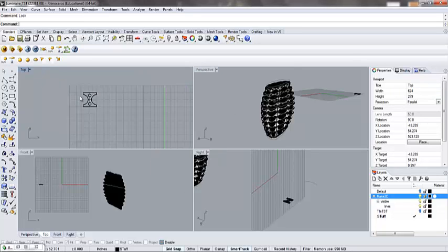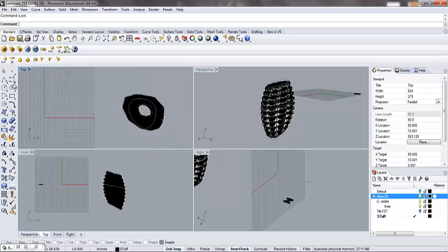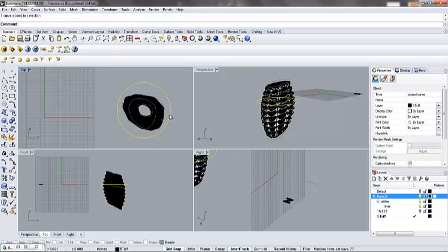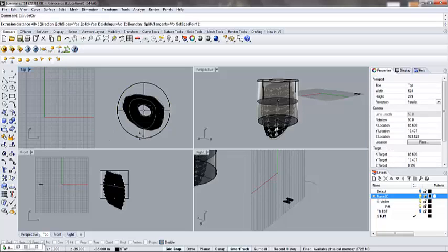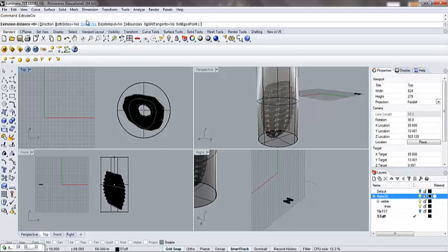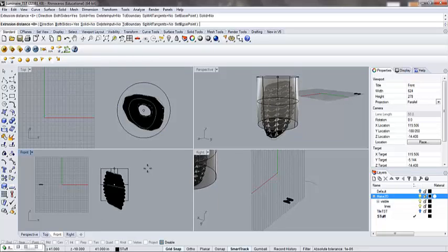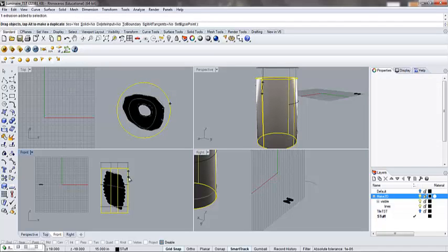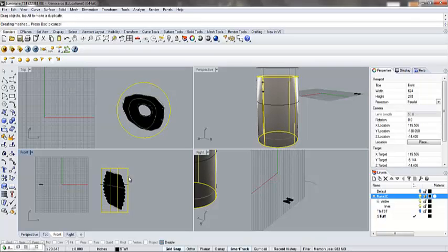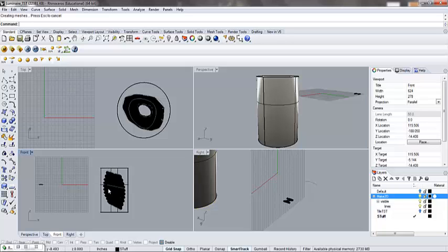From there, for the analysis version, you're going to create a cylinder around the luminaire. And I want you guys to try and get this around 1 inch all the way around, and I'll let you guys actually measure that. Then we're going to go ahead and extrude that curve. I'm going to turn off the solid component of this, and we want this to generally be about the height of our guy, give or take here. About 1 inch in either direction as well. So we have 1 inch, 1 inch, 1 inch, 1 inch all the way around.